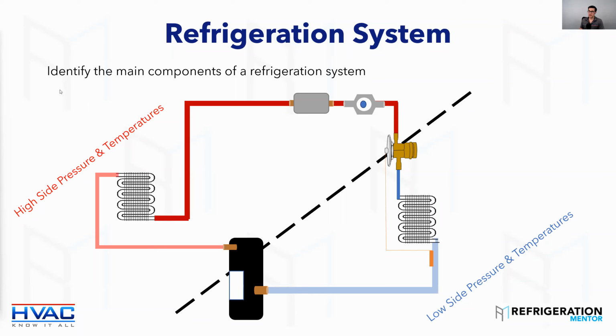And you'll see it sometimes, and I've seen it doing field support many times. A guy calls me up and he'll say, "Hey Trevor, I've never seen this before, but my liquid line is cold and my suction line is warm." Okay? And I've seen it before where the condenser's plugged. I don't know if any of you have seen a condenser plug, but you get a plug in the condenser and then it's going to be flashing in there. Now you got a metering device inside your condenser, or you got a plug.